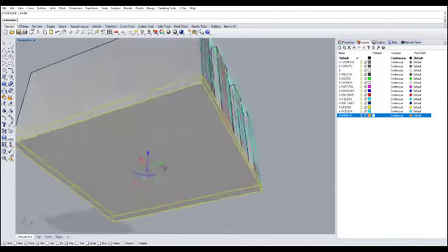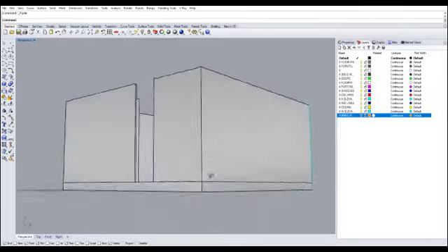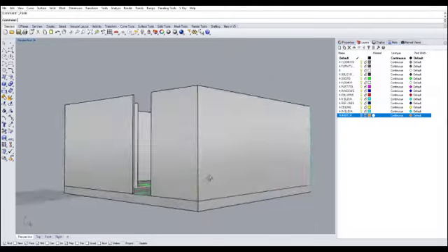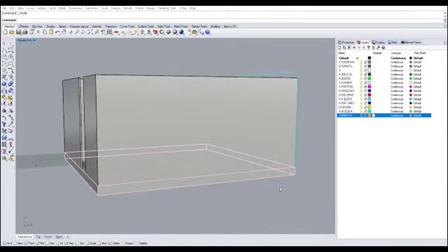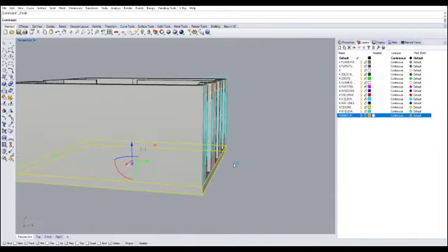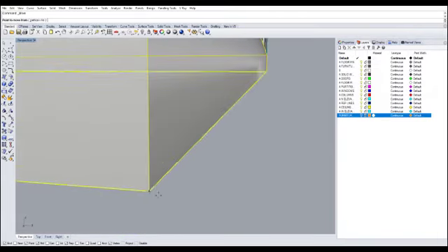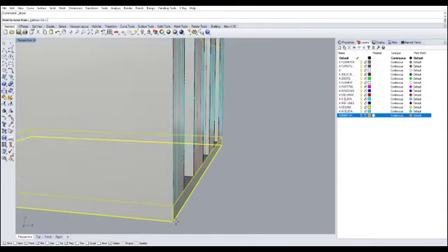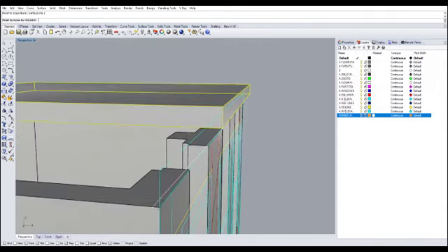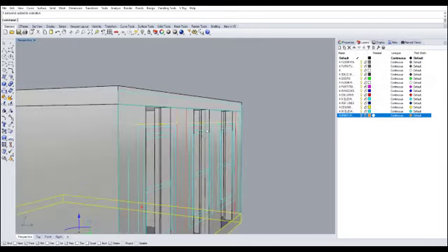Control-V to paste. Now, it doesn't seem like there's anything new there, but there really is: the floors are overlapping once again. The duplicate floors are overlapping together. In fact, if I click on one of the floors, it tells you there are two extrusions. So let's select one and use the move tool to move it up against the beginning of the ceiling line. Again, the beginning of the floor line against the beginning of the ceiling line. We're only moving one of the duplicates, and it should lock up nicely right there. See, the original is still there.